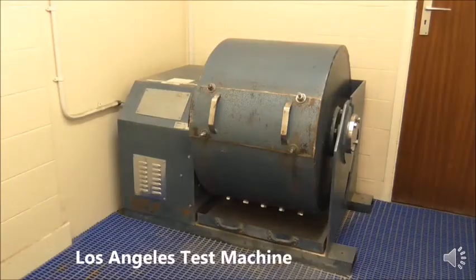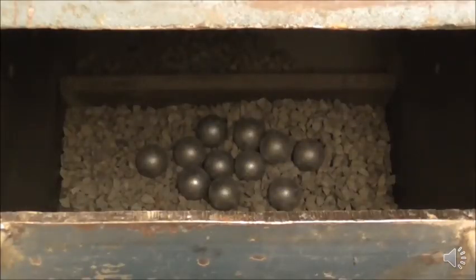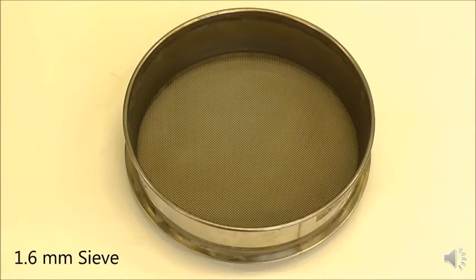Okay, so this is a test that is done by a company in Britain. So the principle of hardness is determined by the Los Angeles test. First, you get your sample of aggregate. It's 5 kilograms. It's hard without the narrator. But what they've done, they've taken the sample and they've put it in a sieve.